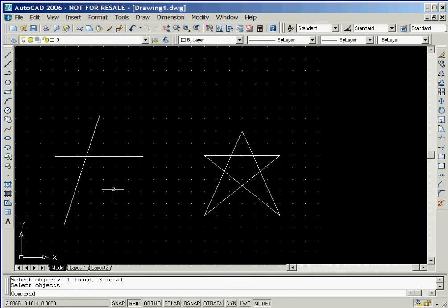We'll now click the right mouse button. The process of right-clicking tells AutoCAD that we want to accept the selected lines and erase them. Another technique that can be used to erase lines is to first select the lines and then give AutoCAD the Erase command. We'll illustrate this by moving the cursor above and to the left of the remaining lines, and then clicking the left mouse button.